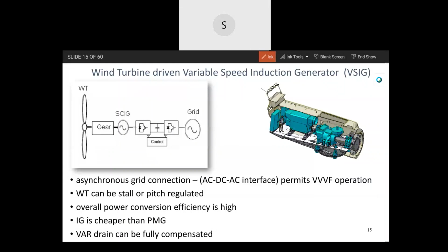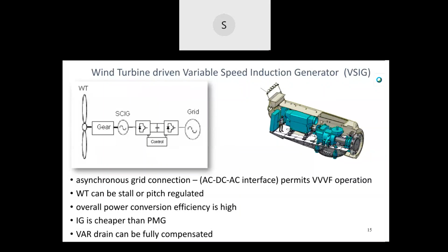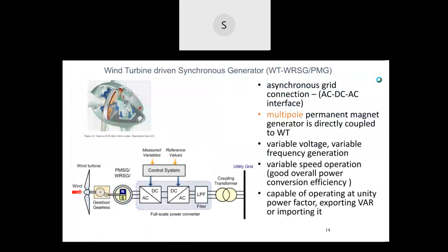But still, when synchronous machine was brought to replace induction machine, electrical engineers were wondering, oh, at least for some things it's unfit for power generation. Conventional power generation also we are not using. But then the question came that the synchronous generator you are using is not in synchronous mode. In a conventional power plant, you are using a synchronous generator synchronously connected. But here it is asynchronously connected. The entire power is rectified, and then AC. If that is the case, this is possible.